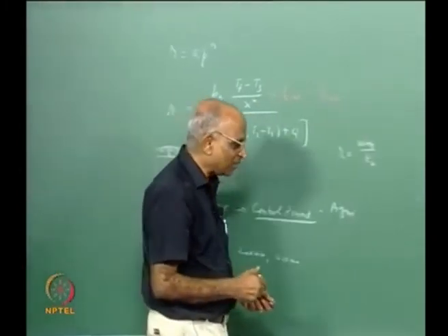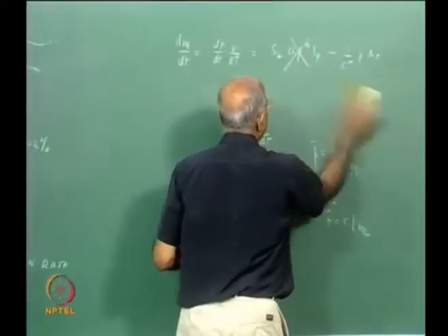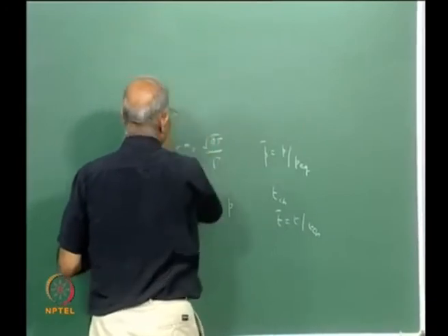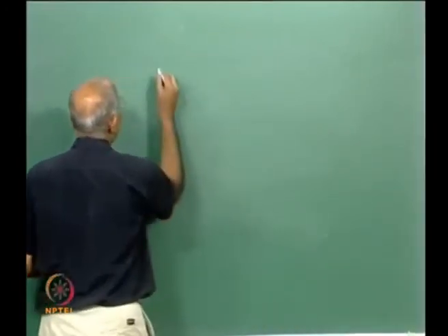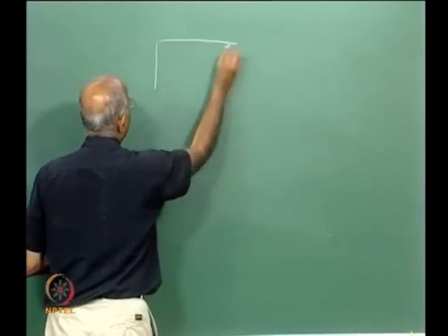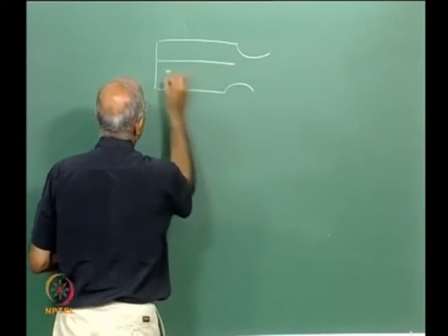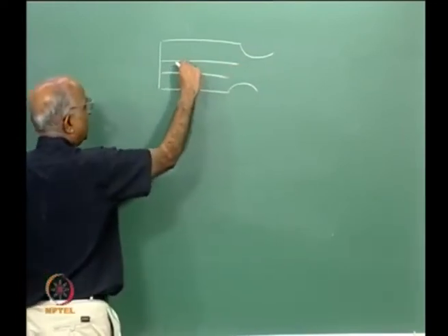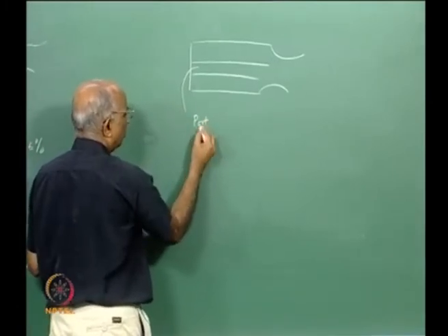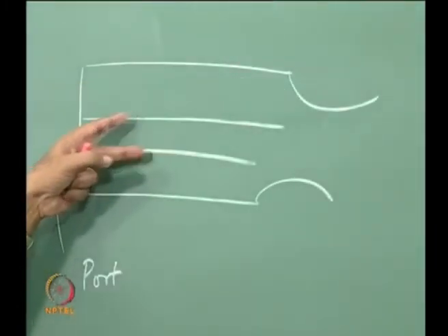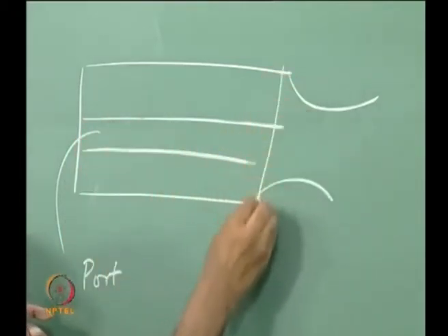This brings me to the last point, namely if we were to have something like a long propellant grain, like let us say I have an internal burning grain, let us say radial, the initial cavity diameter, which is also defined as the port of a rocket motor, that is the port cavity, is of small diameter and it burns at the surface.